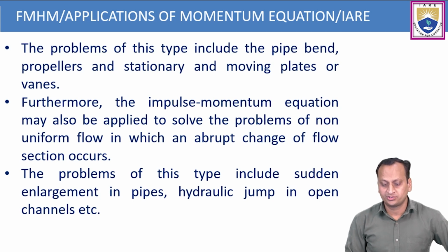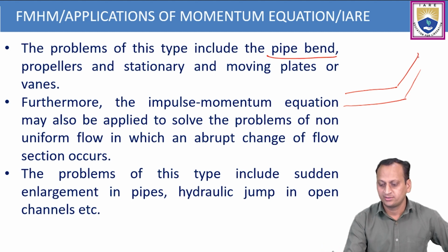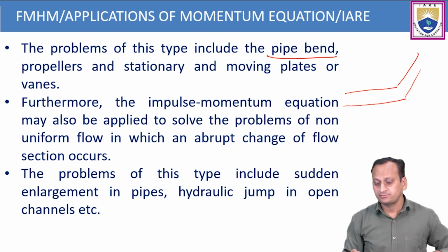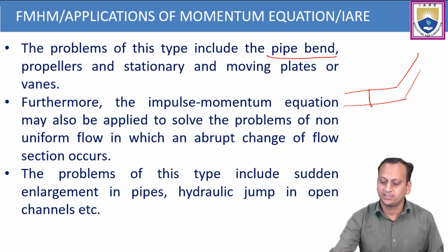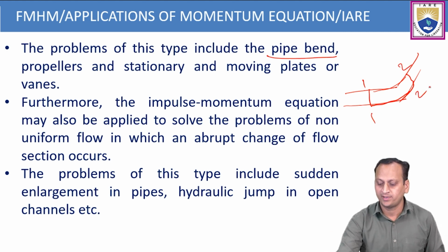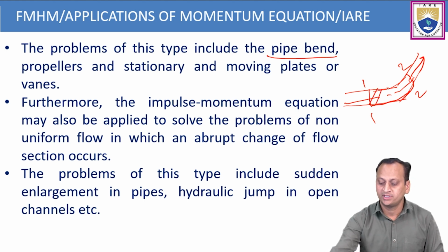The problems of this type include the pipe bend. Majorly, it can be applied on a pipe bend. The pipe bend will be in different diameters and different orientations. For such a pipe bend, we can consider a particular control volume. In this region, we apply the impulse momentum equation to find the various forces, and various other unknown parameters can be calculated. Before that, the first thing is we have to consider a